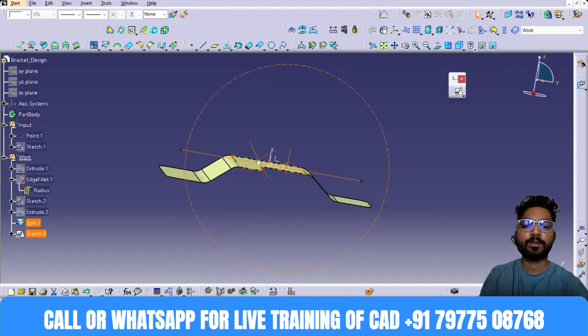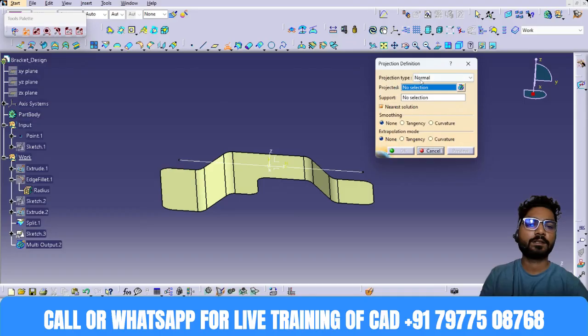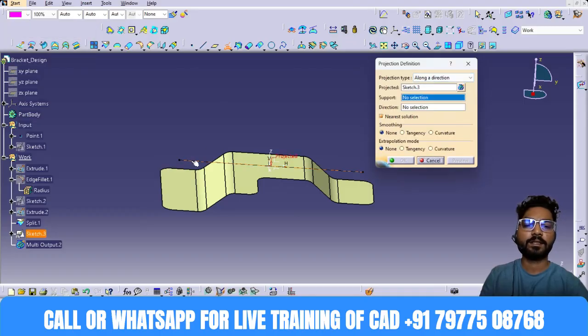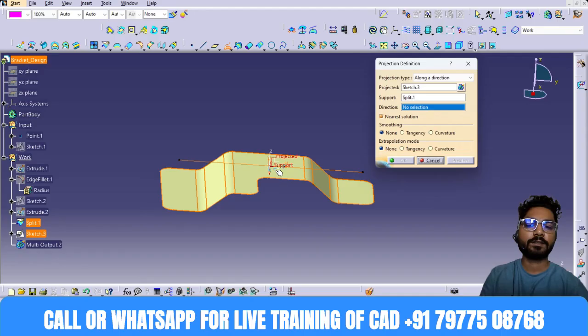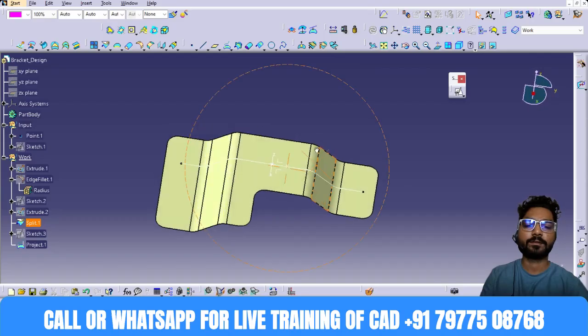And now what I am going to do, this line I want to project onto this surface first. So I will select the projection along the direction, and this line I want to project on this surface. Direction is your Z direction, or you can see the XY plane also. So you can see that line is projected properly onto your surface.